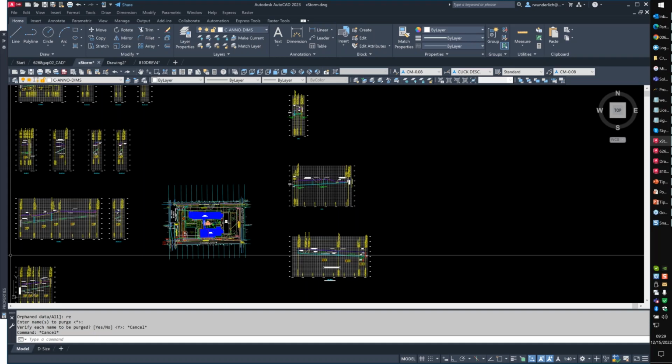If we set XREF reg app control to 1 in our AutoCAD doc, is this going to continually purge out or eliminate data from LandFX? No. The only thing that you're doing with the XREF reg app control is that it controls when you bring in an XREF that it does not bring any registered applications from the XREF and put it into your drawing. It's not going to change anything with LandFX. And if you do a minus purge and purge out the reg apps, if LandFX is purged from there, the next time you start anything with LandFX or you add anything with LandFX, it gets put back in. Most likely, if you already have LandFX data in your drawing, it will not be purged, and it should not.